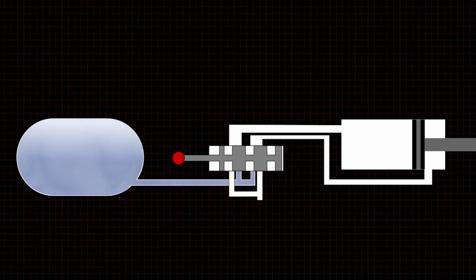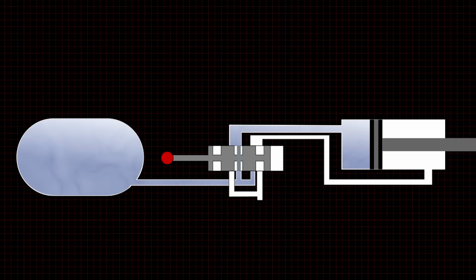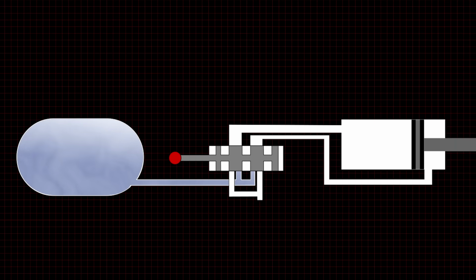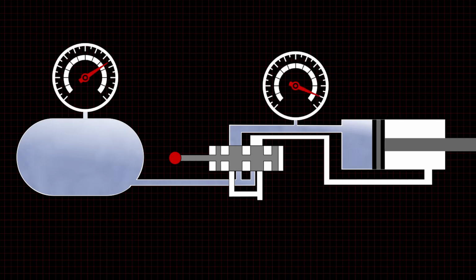In double-acting systems, an additional valve circuit is connected to the opposite side of the actuator. As before, the side of the actuator not under pressure expels its volume to the atmosphere. In either system, the actuator can move due to the changes in load, even if the valves are closed, because air within the actuator is compressible. It behaves like a shock absorber.